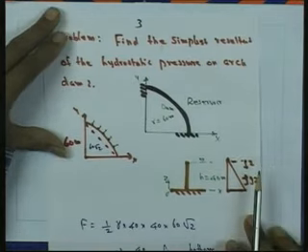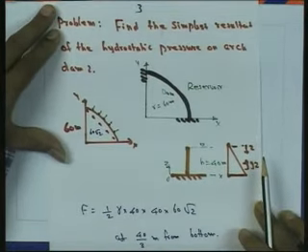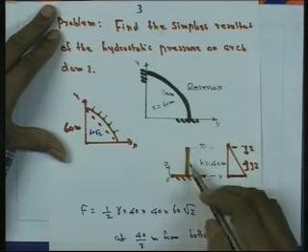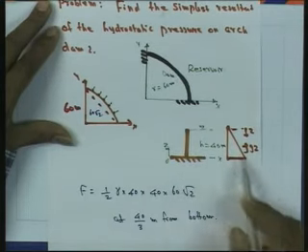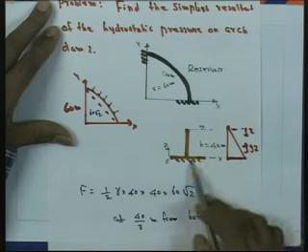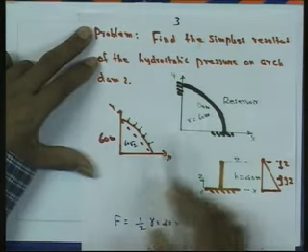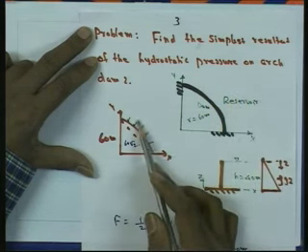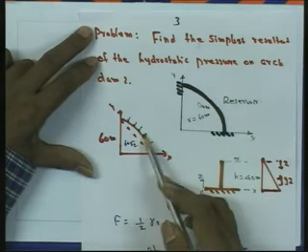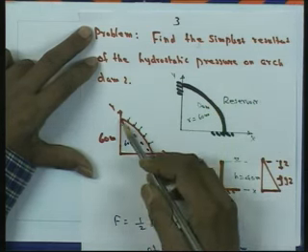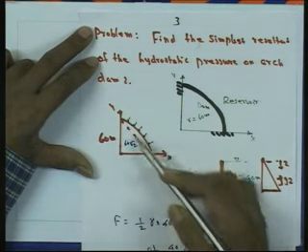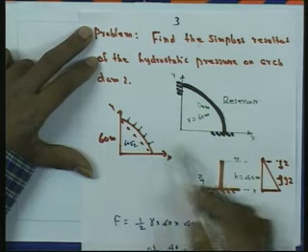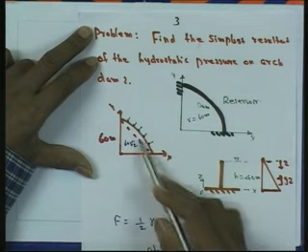With respect to this figure, first we will find the pressure distribution at the bottom of the dam. Here it is 40 meter, so it will be rho g into z at the bottom. In this figure you can see that due to the effect of the reservoir, the force will be acting normal to the surface. In a simple way, we can take this inclined plane as an approximation. So, we can find the length of this inclined plane. Here this is 60 meter radius, so we can find that this will be 60 root 2.